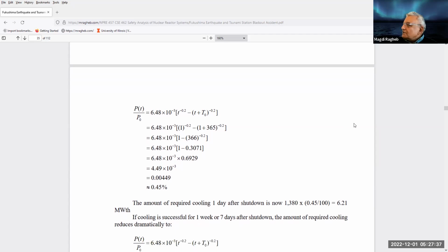That's why the new designs of nuclear power plants emphasize ways of dealing with that decay heat. One solution is to progress from using solid fuels. In that case, as you know, the fission products remain in the fuel, and then the plant is refueled every year or a year and a half. If you use a liquid fuel like a molten salt, you can continuously extract the fission products, and that accident would simply disappear from the annals of nuclear energy generation.